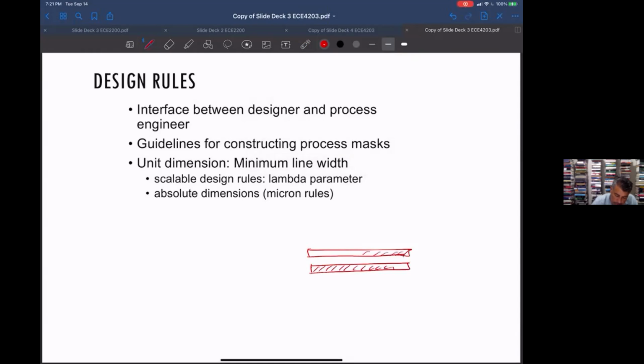So put your mask on. If I was going to look at this from a cross section, from this edge, it would look like 2 polysilicon gates, looking at it from this end as a cross section. So this would be the silicon, this would be polysilicon, and this would be some oxide. Okay, that's what it's going to look like.